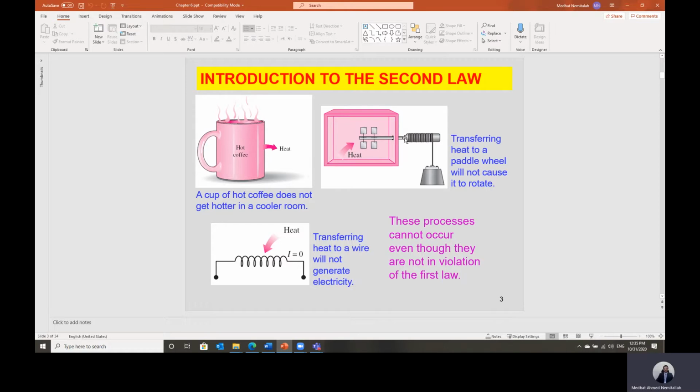We burn the fuel to have heat. Then inside the engine, we can move the pistons, then we can convert this heat into shaft power, in this case to drive the car. So to convert heat into work, we have to have what's called a heat engine, and it should work on a cycle in order to generate continuous work. But by adding heat outside the heat engine, we cannot move the paddle wheel to convert it to work. So that means this process has only one direction.